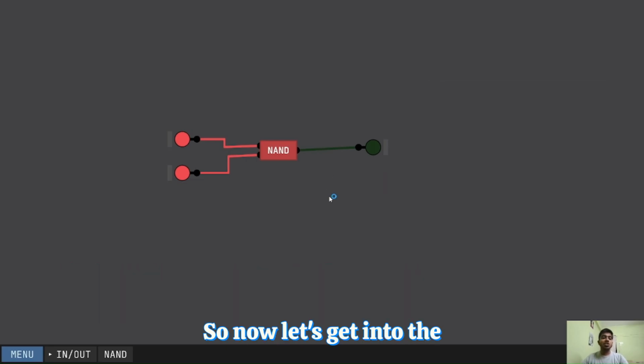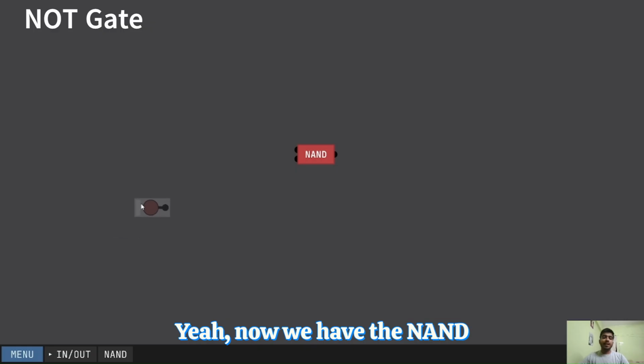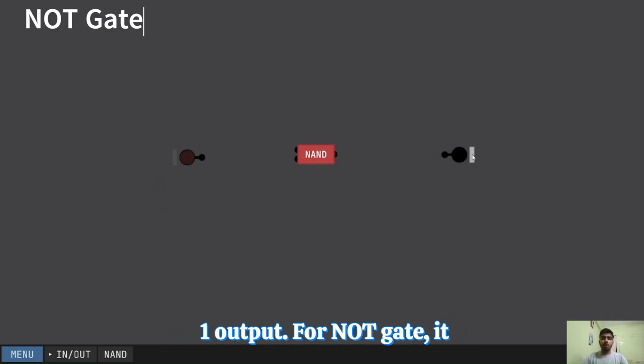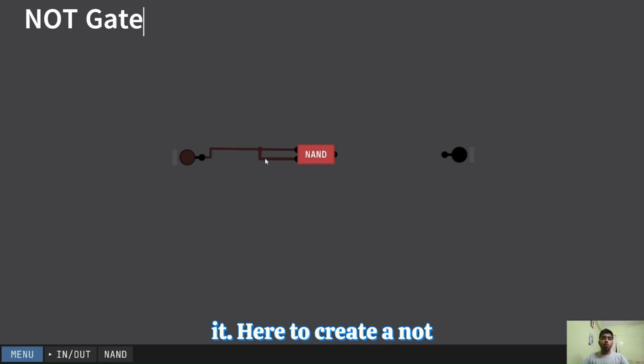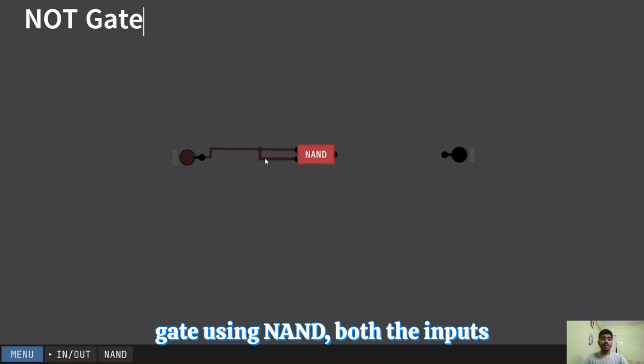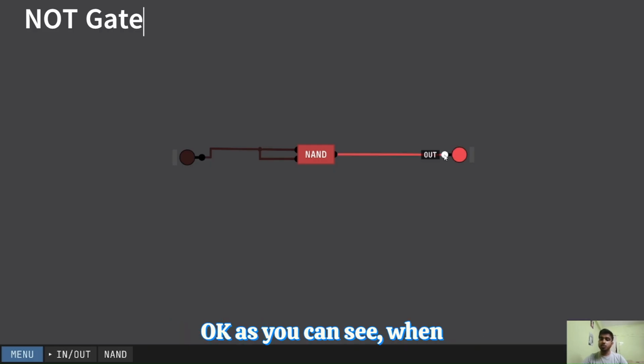So now let's get into the NOT gate using the NAND gate. Now we have the NAND gate with one input and one output. A NOT gate only consists of one input and one output. So let's connect it. Here, to create a NOT gate using NAND, both the inputs are connected together, and this configuration behaves exactly like an inverter. Let me show you that.